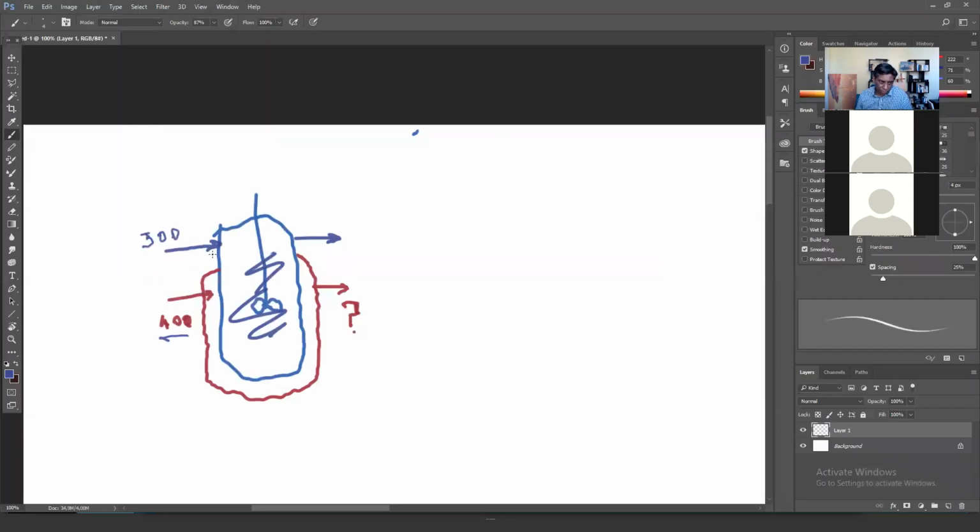For the temperature on the reactor side, assuming that T is the same everywhere, that's more a consequence of perfect mixing, right? So that has nothing to do with space-time. We are assuming one temperature in this reactor, and that's just because everything is so perfectly mixed, right? In a CSTR, we assume infinitely fast mixing. So we've got the same temperature at all points in the reactor, including on the walls. And so that's why we treat it as just one temperature T. But it's an unknown temperature T, right?